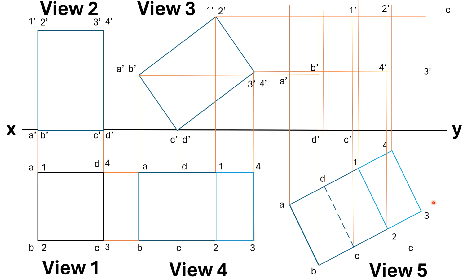Now we are seeing the front view. When you see the front view, from this side, since this is the top view, all these edges will be visible. That means if you draw an imaginary line joining the leftmost corner to the rightmost corner, the edges below this line will all be visible in the front view. Because we are seeing from this side, all these edges will be visible.